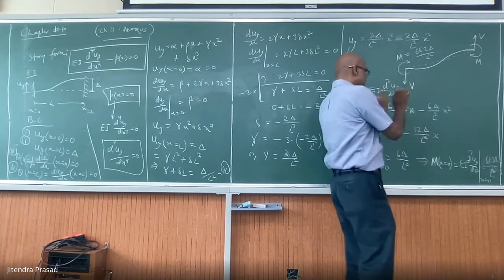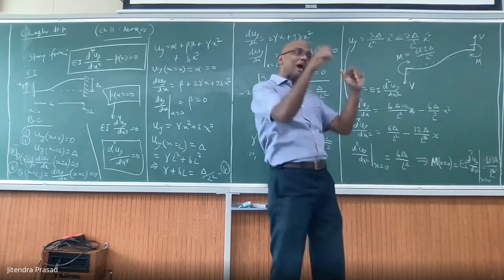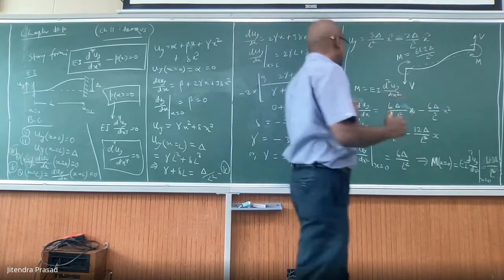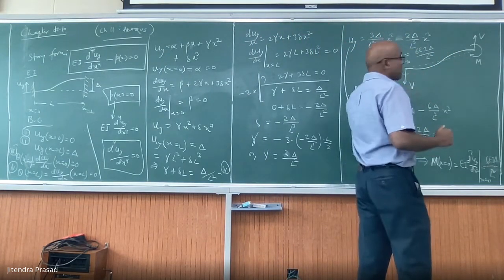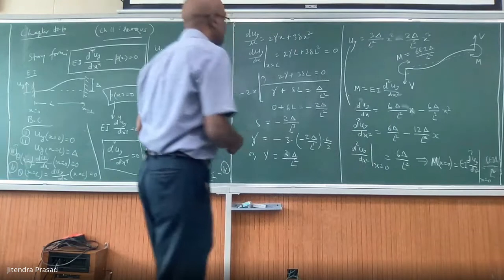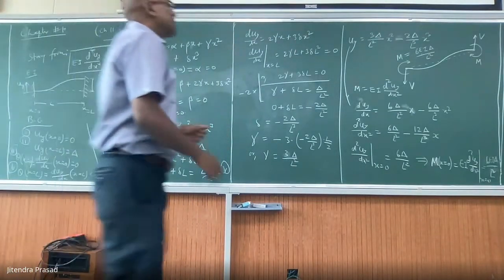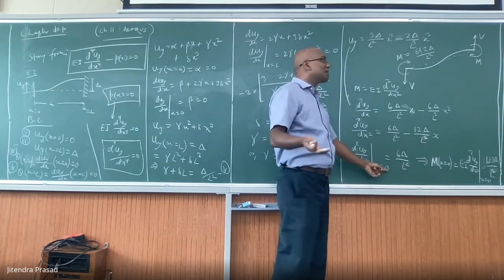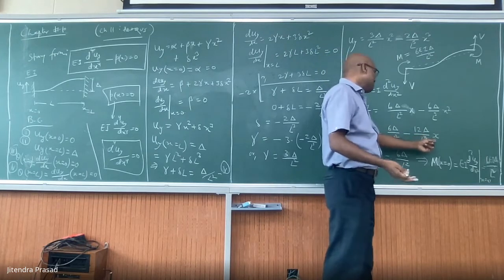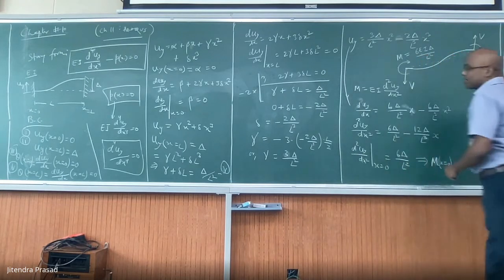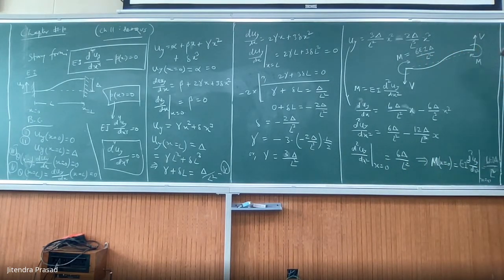And this will be like this because when we derived it, the sagging is positive. So for both the sides, from this side clockwise is positive, from this side anti-clockwise is positive. Okay. Well, if you put x equal to L, you will get minus. Minus means it is clockwise here. The other end it's hogging. Yes, you will get minus.